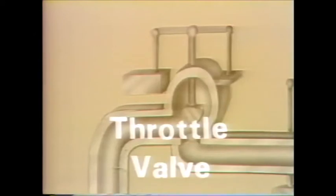Now, before steam can enter the turbine through the steam inlet, it must pass through 2 types of valves: stop valves and control valves. Stop valves, alternately called throttle valves, remain fully open during turbine operation. The principal function of stop valves is to shut off steam supplied to the unit during shutdown or under emergency conditions. Control valves are used to regulate the amount of steam flowing to the turbine.